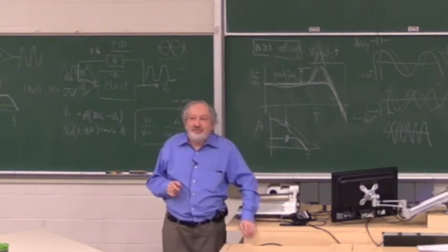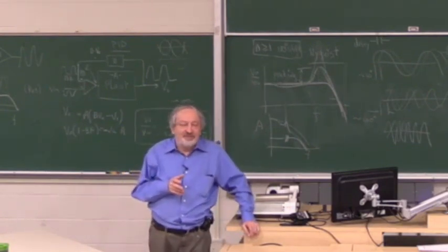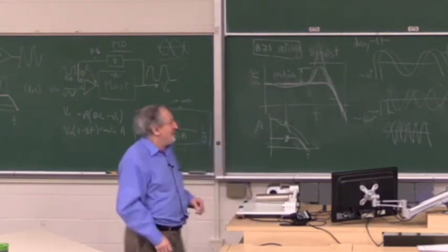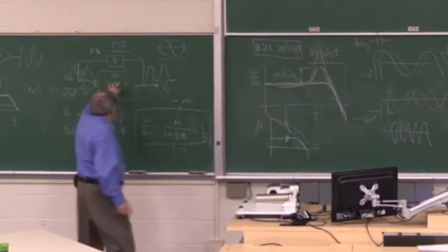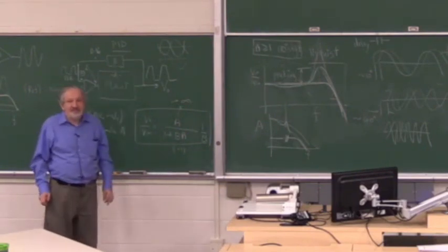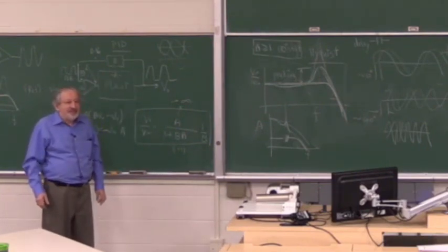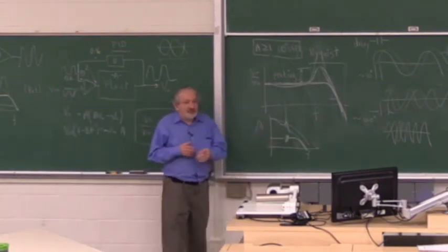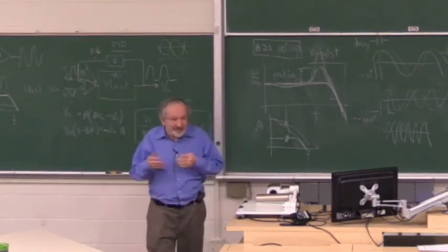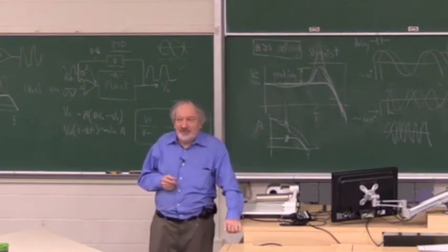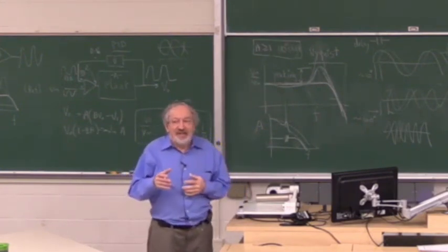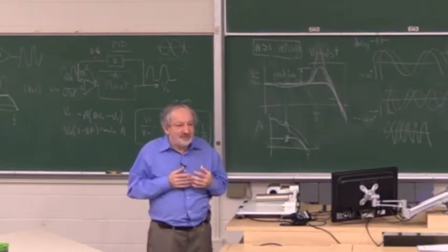So the two big problems in servo systems are delays, which cause phase shift, and delays usually come from the plant, not from the sensing. We'll talk about it later. And if you have any resonances, they cause huge phase shifts and delays. But the biggest problem is when the output is not in phase with the input.